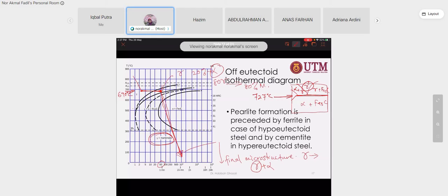So you can modify, you can customize this. Okay, you know the ferrite is soft and martensite is hard. Okay, if you obtain 20% of softness and you measure the hardness, you measure the tensile strength, you measure all the properties, you think that, oh, there is room for improvement. I want to increase the strength a bit. So for that, you can increase this, okay, to 30% maybe. So how much will it influence?